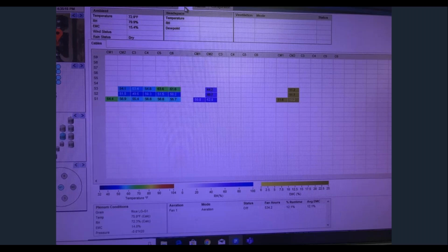Addition of this grain management system has basically increased our capacity in the bins by 15 to 20%. Before we had this, we had mechanical stir-alls in the bins, which didn't allow us to fill the bins up. Now we can basically fill them up to their capacity. So it was basically like putting up two more 48-foot bins with just the addition of this system.